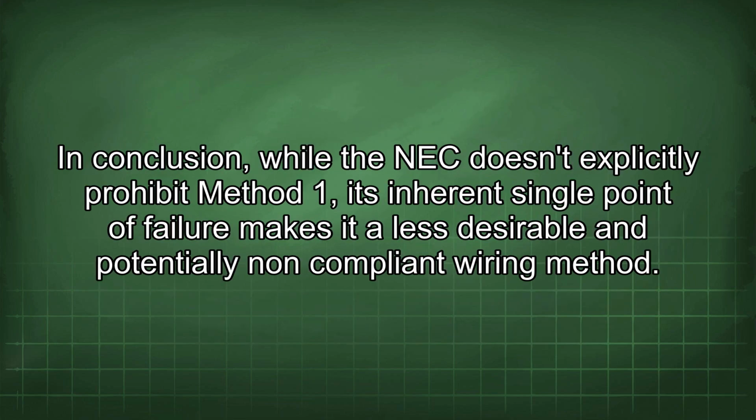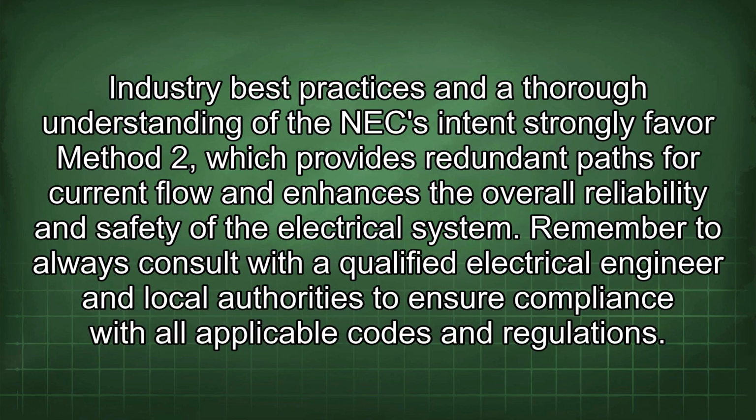In conclusion, while the NEC doesn't explicitly prohibit Method 1, its inherent single point of failure makes it a less desirable and potentially non-compliant wiring method. Industry best practices and a thorough understanding of the NEC intent strongly favor Method 2, which provides redundant paths for current flow and enhances the overall reliability and safety of the electrical system.